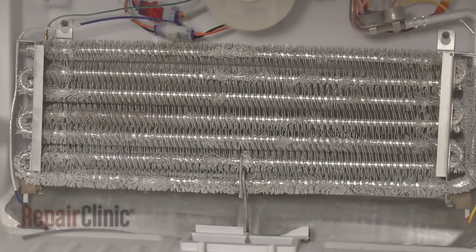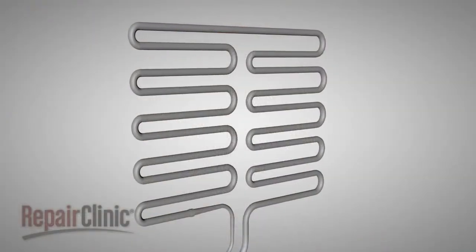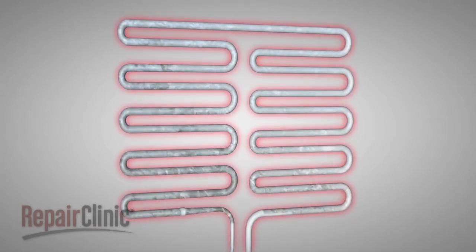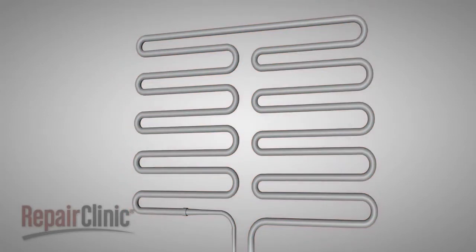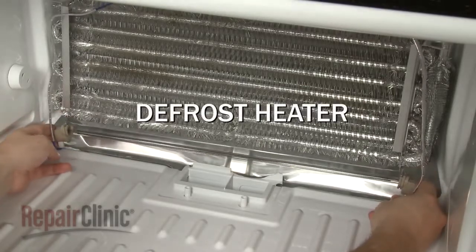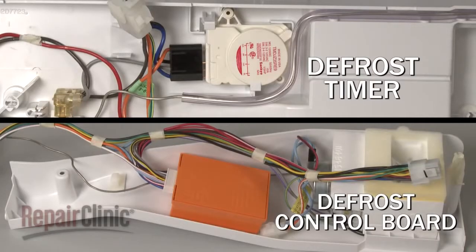As we mentioned earlier, the evaporator coils collect frost as the air from the refrigerator passes through them. Since frost buildup can cause airflow problems, the coils require periodic defrosting. Older models needed to be defrosted manually, but most of today's models use an automatic defrost system. The basic components in this system are the defrost heater, the defrost thermostat, and the defrost control. Depending on the model, the control may be a defrost timer or a defrost control board.